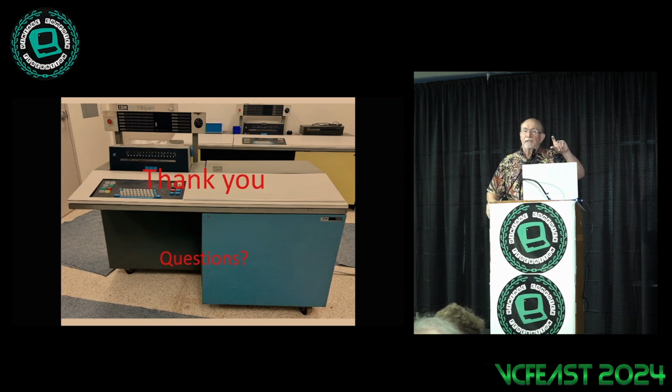They didn't need it because, remember, they were never taking signals in and matching them to a clock edge because it's not a clock synchronous machine. I mean, there's a clock, but that's sort of a reference point. It's like here's something that says it's time 3 and it's during the plus phase, but that's not when signals are changing right at that edge. It's just something that's combined combinatorially to decide when something might happen. Instead, everything happens with that AC triggered one when the pulse actually happens.